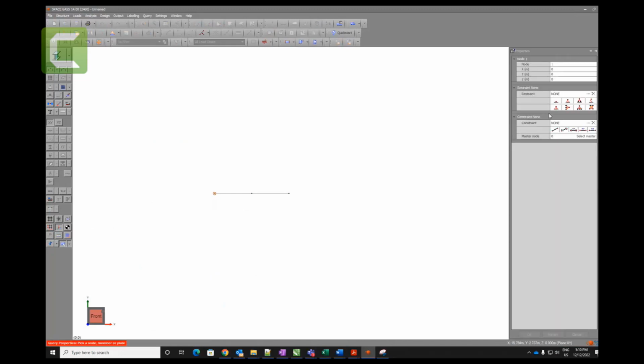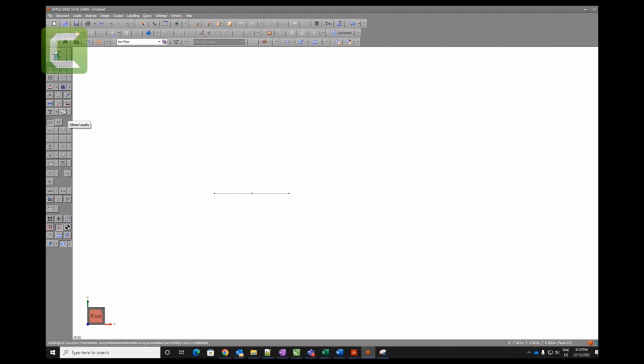If you double click on that one, there is a pin support, which is fixed. The first three letters are for displacement fix, and the remaining three letters are for rotation fix, but there are two rotations allowed. Okay, Y and Z is allowed. So that's okay. We can put these ones here and hit OK. If you don't see these pin supports, you can just click on here. You will see these pin supports.